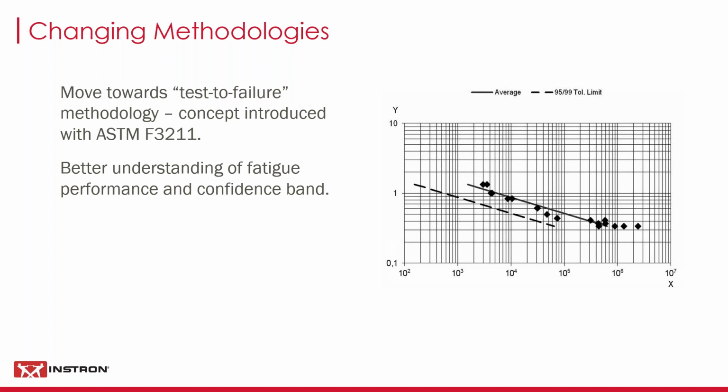We can monitor them live with every cycle. We can look for sudden drops in the stiffness, sudden drop in force for the same amount of compression, for example. And you could look to pause the test at that point and inspect the type of failure that you've got.